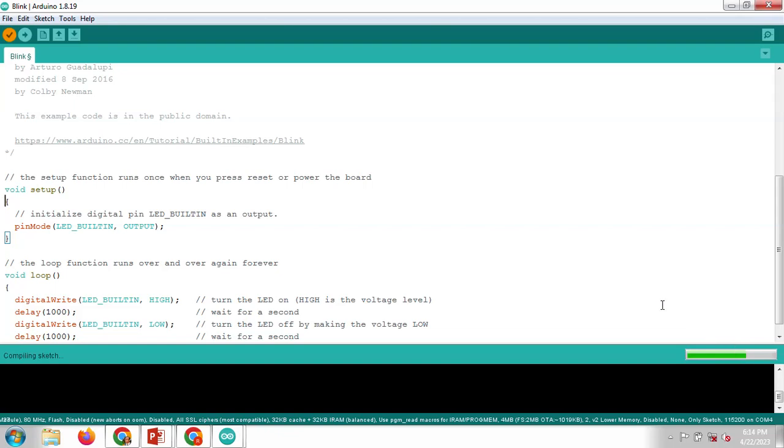After compiling, we can upload this program by connecting the NodeMCU to your USB through a micro USB cable. After compiling and uploading, we can check that the LED turns on and off for 1 second automatically. So we can make different connections. In future, we can connect different sensors, for example a touch sensor or a DHT11 sensor, and check their data either through an LED as an output, or on a cloud itself.